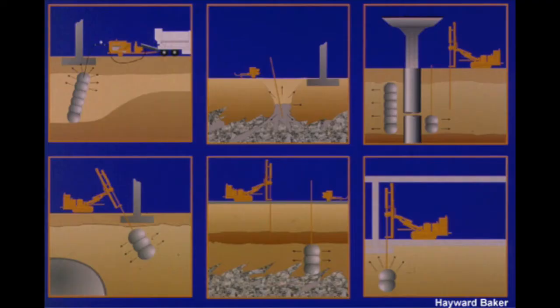As stated in my introduction, soil improvement techniques are also used to mitigate liquefaction-induced damage. Typically, soil improvement techniques are used at sites that have already endured soil liquefaction or under construction with shallow foundations. Therefore, soil improvement techniques that create low vibration are most used. Grouting techniques such as compaction grouting, permeation grouting, and jet grouting are known to have low-level vibration.